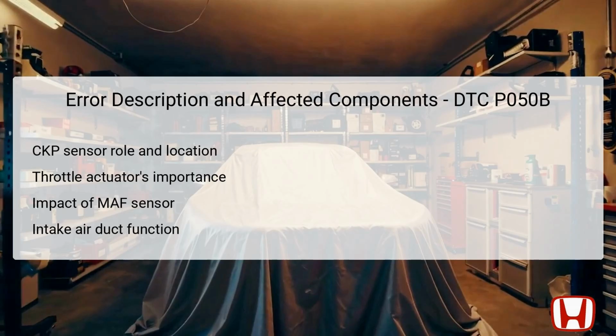A blockage or malfunction in the intake air duct can lead to airflow issues, affecting the engine's air-fuel mixture. If any of these components malfunction, they contribute directly to the performance problems indicated by DTC P050B.